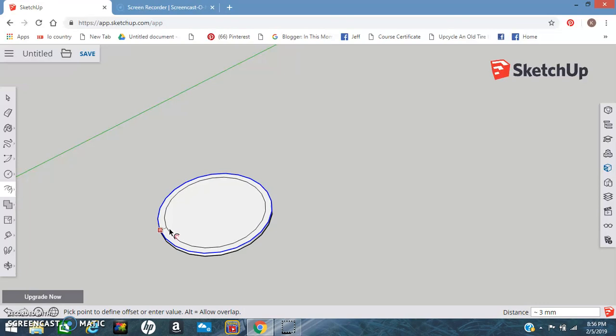In this case, we're going to do an offset of 2 millimeters, which again, if you look in the dialog box in the lower right hand of the screen, you'll see that we have a distance of approximately 2 millimeters. That's going to be good enough for our assignment here. So we want 2. I'm going to click. Now we have a disc with a ring inside with an offset of 2 millimeters.